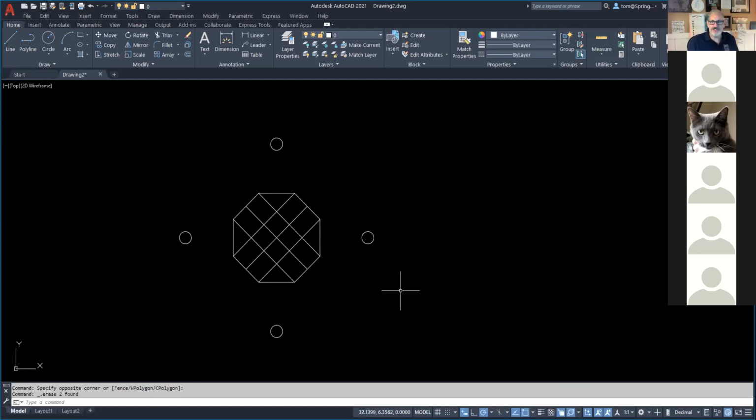Now, one of the things that we did talk about was polylines. We just went over that. I showed you that when you make a polyline, it's all one entity. The other lines I have right here were just drawn with lines. So polylines are always going to be a whole entity. Very useful for drawing building perimeters, because then you can make an exterior wall very easily by using that. Okay, great.